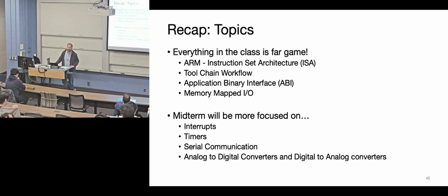Can you explain when things are ACK? It's ACK if it's been received. It's NACK if it's not. Except if you're in a multi-stage protocol, then sometimes those mean slightly different things, like a multi-packet protocol. We're getting confused with this. It's like if the peripheral is driving the signal, the controller will ACK the way the peripheral would have. Yep, it's confusing.